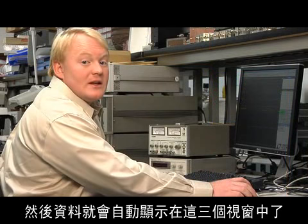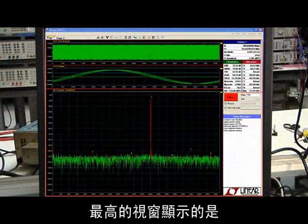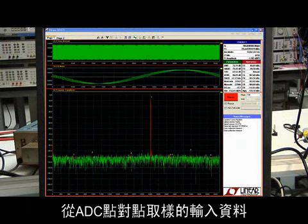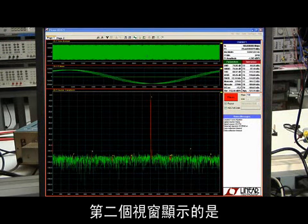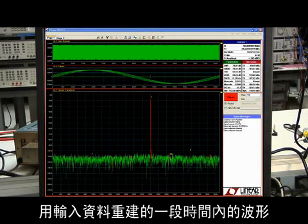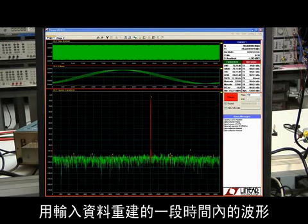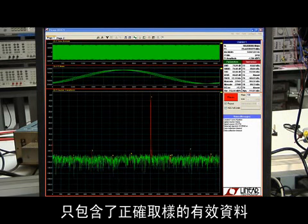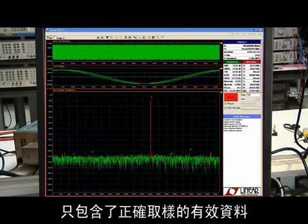With the demo board properly connected, we can hit collect and data will automatically be displayed in these 3 windows. The top window shows the input data sampled point for point from the ADC. The second window reconstructs one period of the waveform from the input data. This is called the P wave or primitive wave. It only contains valid data when sampling coherently.